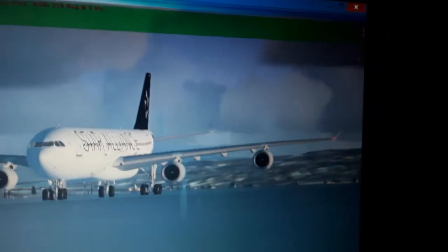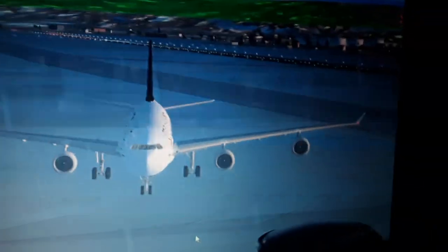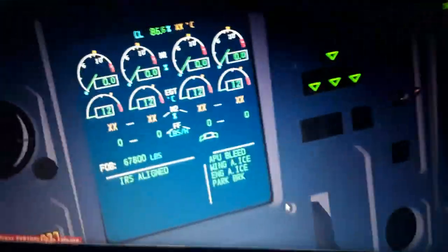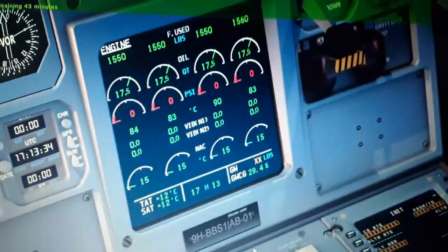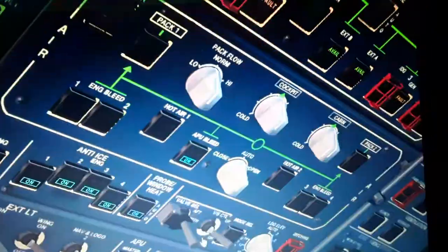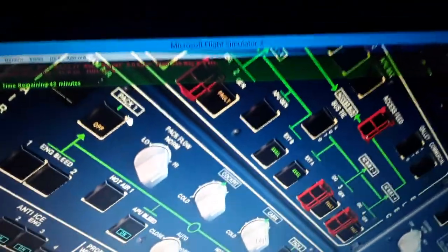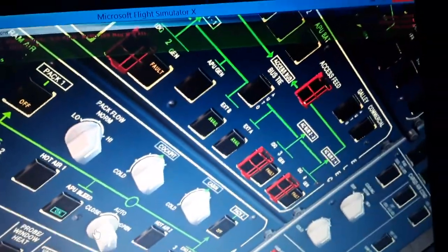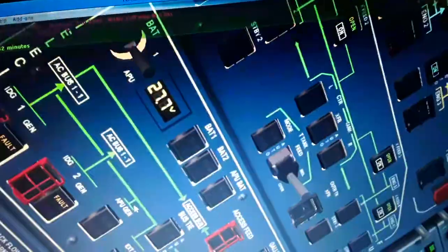So we're gonna turn them on now very quickly. You can see now the axis here display, and here the engine, the secondary. So I'll come in the overhead panel. I'm gonna show you very quickly. The only thing we need is to have the APU on. We can turn the packs off just for display, the left and right pack, in the closed position. And this is all we have to do right now. And we have the fuel pumps on. The electrical is configured correctly, so we'll start the left wing engine first.